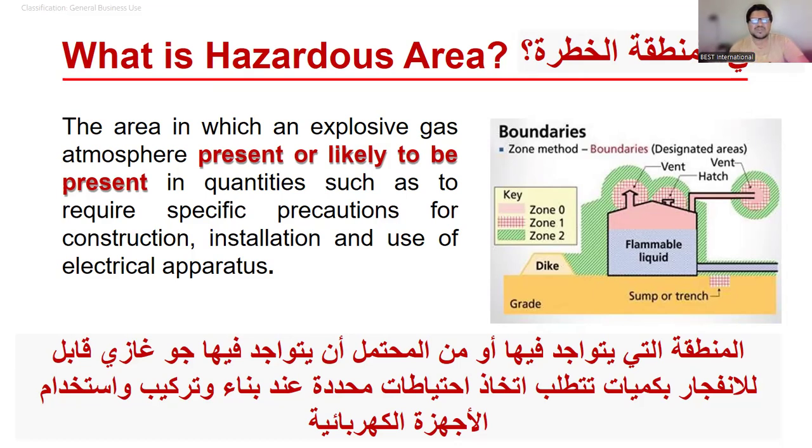They will not allow you because sometimes it starts small, later on it accelerates, and things could get out of control. So Aramco or other high hazard industry top leadership are the ones deciding, and they have to be the right decision makers to allow people to work in toxic conditions. And yes, your safety should be the prime concern. Use the right set of SCBA, self-contained breathing apparatus, or SABA, supplied air breathing apparatus. Still, no harm in having an EEBA, emergency escape breathing apparatus, a bottle available for emergency escape.